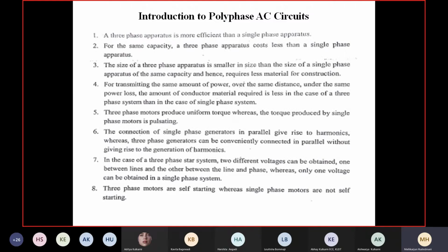The megawatt or kilowatt that each is producing is put in parallel with the neighbor and others, which we call a parallel. They are supposed to inject the power into the transmission grid. When I connect them in parallel, definitely it will have an influence. Are you doing three phase or single phase? If it is three phase, three phase generators run in parallel very smoothly. They will not cause any adverse switchings or harmonics in the system, which are unwanted inductions.